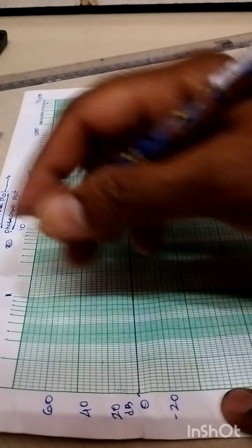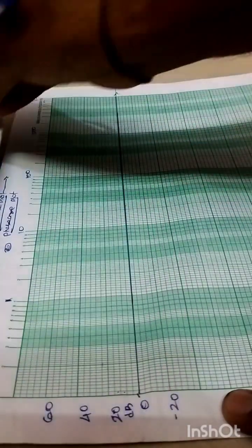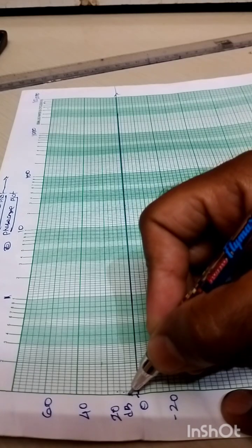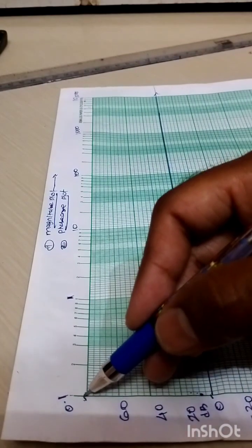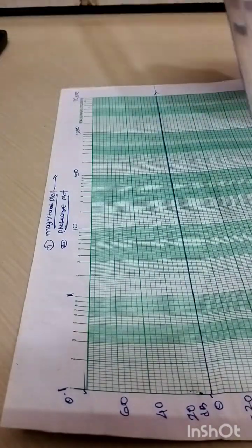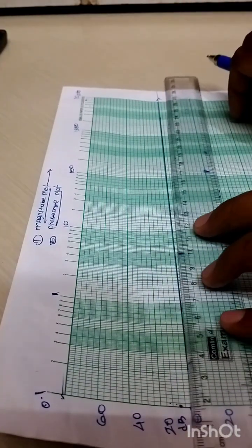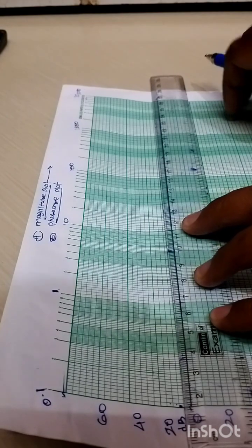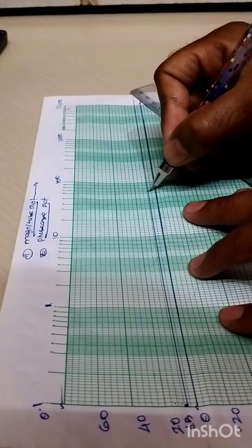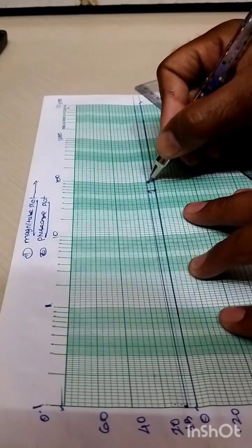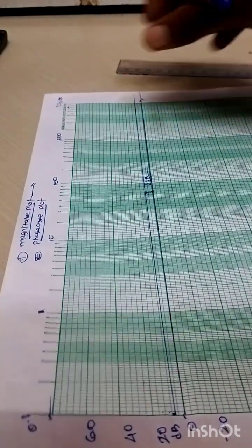So we need to plot this factor at how much dB? At the 6 dB line, right? So this will be the 6 dB line, which starts at point 1 and ends at infinity, right? Accordingly, first of all we need to draw this 6 dB line. Here the gain is 6 decibels, right? This will be the first factor, right?